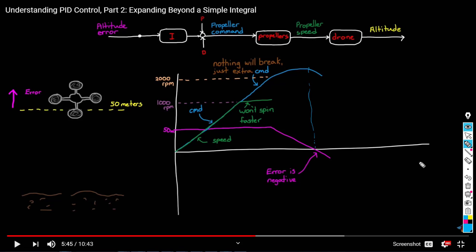In reality it's better if my blue curve, my command signal, was like this: when it's saturated, it will saturate, and in here start to decrease my control signal, because the error is decreasing at this point. Here where the error starts to decrease, I should react here.